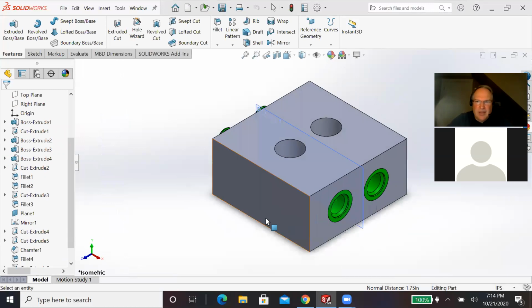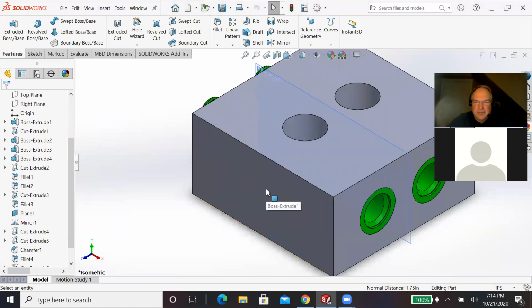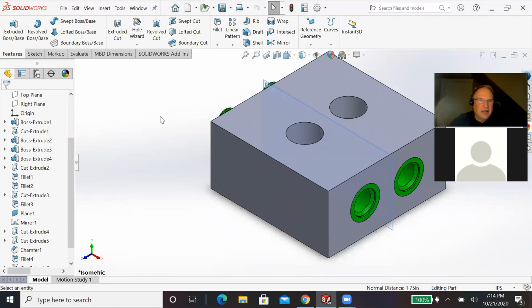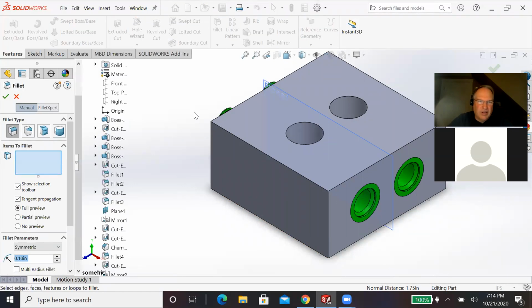So now, when we're looking at it here, we got to add some fillets on all the corners. All the corners are filleted. Obviously, it's some sort of a kid toy, so it's got to be safe. You don't want those edges on it. I think it's 0.13, not 0.3. 0.13. Pick.